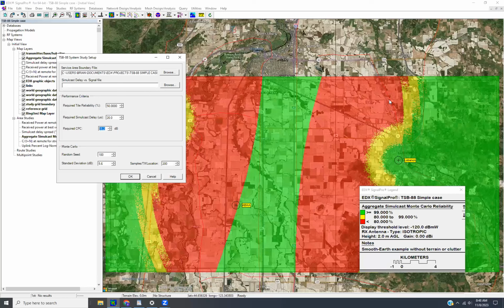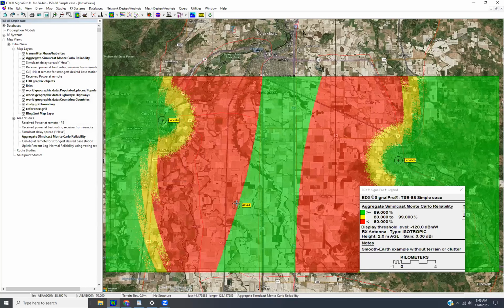Follow-up question on the receiver noise figure, which is, does that account for the feed line, isolators, jumpers, and such? And that's where I think it does not necessarily account for all the connections and every item that you might have in your block diagram. So if you're accounting for each of those things specifically, you may want to hand calculate your noise figure and populate that in there.